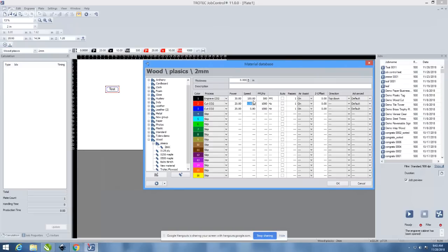So just make sure, guys, that you're careful with your engraving settings. It happens to me almost weekly. You're trying to get your settings in quickly, and instead of 1, you might type in 100, and that is not going to be good for your file or your material. Or vice versa, you might type in 0.80 for your engraving, and of course, that's going to be way too slow to engrave anything with any good quality. But just keep an eye on that, guys, and you should be fine.